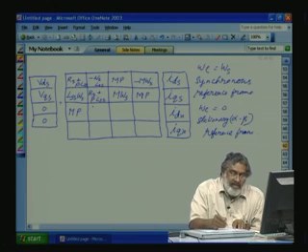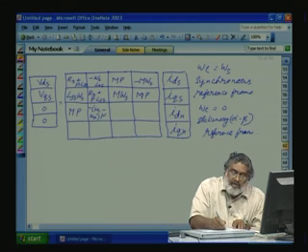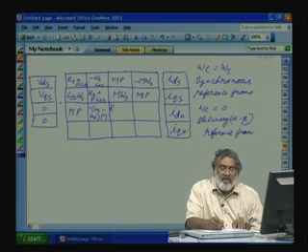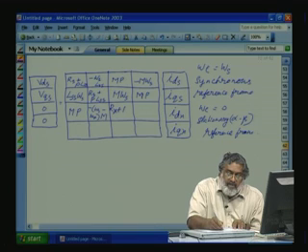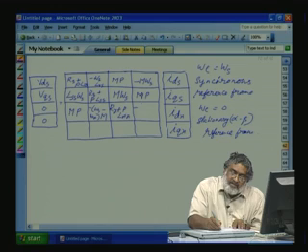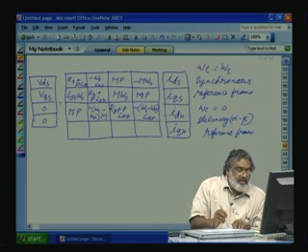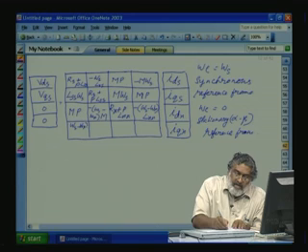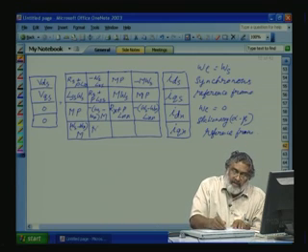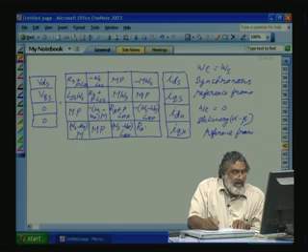Again here m into P. For the rotor, the relative speed is omega s minus omega r, so minus of omega s minus omega r into m. Then the rotor resistance and self inductance drop, RR plus P into LRR. Then minus omega s minus omega r into LRR. So the rotor D axis voltage row is over. Now the rotor Q axis: omega s minus omega r into m, m into P, omega s minus omega r LRR, then RR plus P LRR. P is d by dt, as an operator.